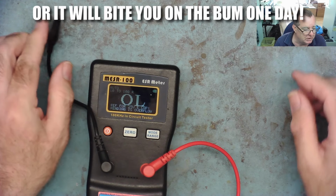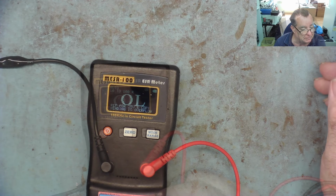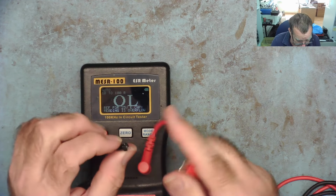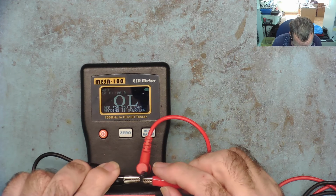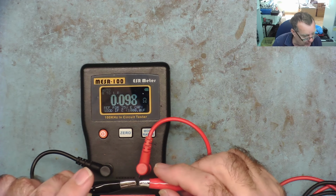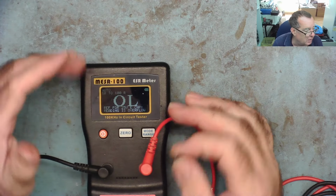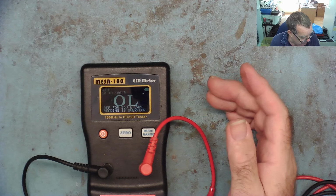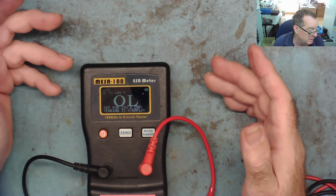I'll just get one or two non-low ESR capacitors. These are not low ESR. Let's just use them for comparison. This one doesn't say it's low ESR, but let's try it. And you can see that's reading much lower. So even with good capacitors, you can use your ESR meter to select them when you're building projects, especially if you're using salvage components. That's another very good reason to have an ESR meter.